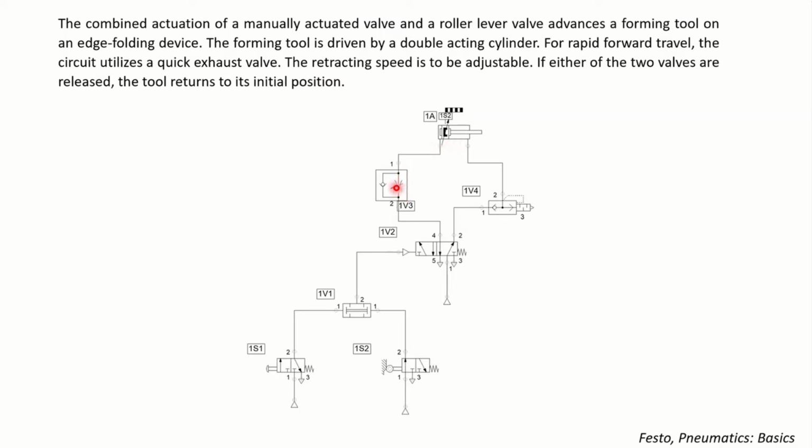And because we have this throttle valve, again the air comes here, and it can go from this side first, or this way. First it checks this side, and this ball blocks the path of the air, therefore the air should pass this way, right?